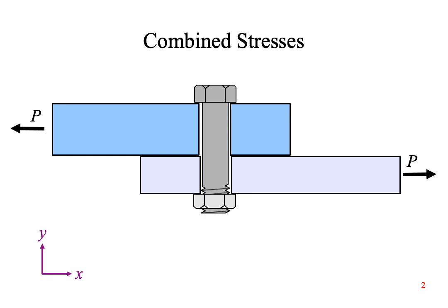Bending and shear stresses develop in the head of the bolt because the head wants to stay put while the shank wants to pull downward. There are shear stresses in the threads of both the nut and the bolt acting in the y direction. It looks like a pretty simple device, but a bolt has to support a combination of many stresses in different directions.